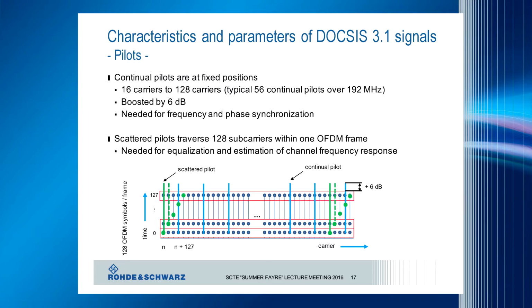Here, some slides means one slide. So, together with the standard here, OFDM, it's also common to talk about pilots. It's not new, it's also used by DVB-T2, for example. So the pilots are very useful and have different, let me say, tasks within the signal. So we have to distinguish between two kinds of pilots: continual pilots and scattered pilots.